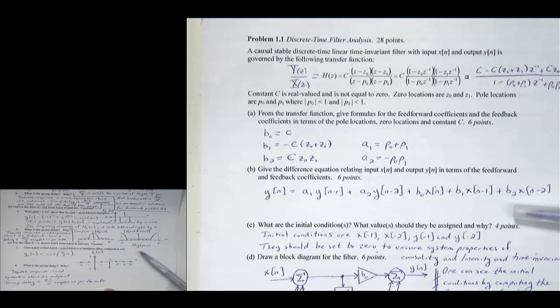So some folks correctly noted this is infinite impulse response. If you think about it, it's not a filter, it's unstable. But it's an LTI system that's two-sided, a two-sided signal. And so about half a dozen of you said, okay, if I want a bandpass filter, I'll just go ahead and design an IIR filter with the poles in the right location.